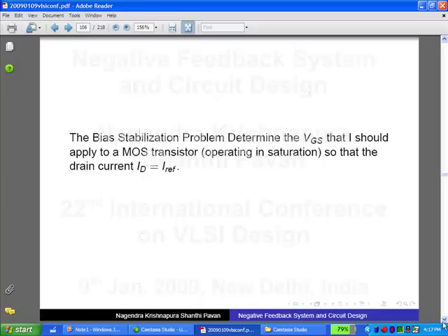You're doing the opposite thing, right? You're given VGS, find I. But in practice, in design, you do exactly the opposite thing, correct? I want I, tell me what VGS I must use. In a transistor, what is the cause and what is the effect? VGS is the cause and I is the effect.